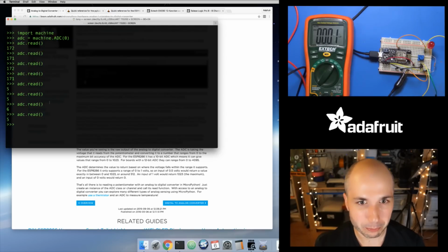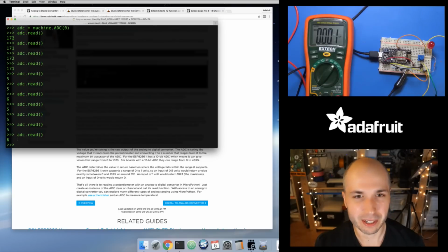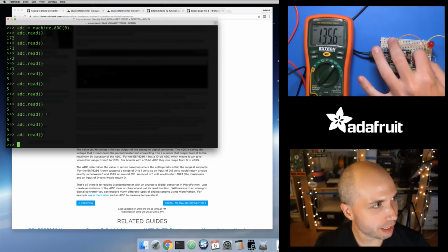If you see totally random fluctuations, like if I keep calling this and I get 5, 6, and then 100, and then 30, and then 5 again, and then 100, that's a little weird. Something is wrong, so make sure your wiring is okay. You should get pretty similar values, but they might change. And if this is a problem, one thing you can do is call read multiple times and average out those values. That'll smooth it out and give you a value that doesn't change as quickly, something a little more stable. It's a real nice, easy way if you're trying to change the behavior of something based on the position of a potentiometer.